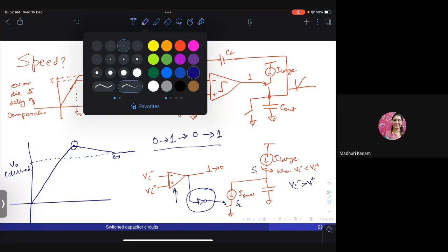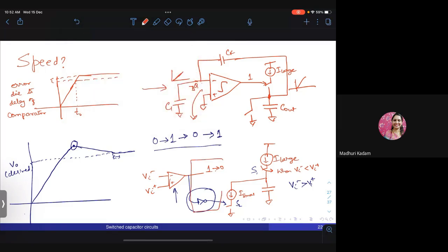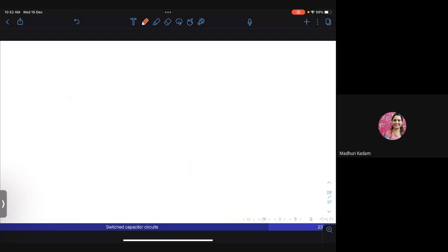So basically, there is a small digital circuit between the comparator and the switches. So this is a simple digital FSM which will detect that sequence. Yeah, very easy to design. In fact, it is something which second year students do in our courses, right? You just have to write that RTL code, and it is very simple. Yes, sir. Okay, understood, sir. Thank you, sir.